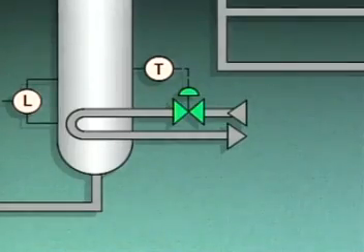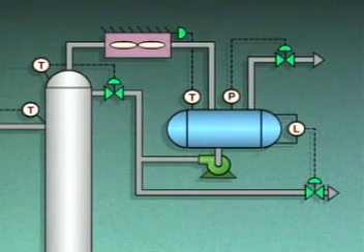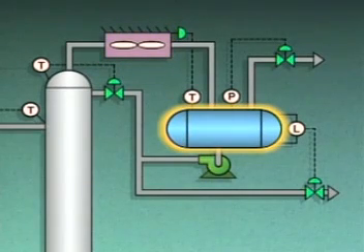The control system's energy balance control loops react to an increase in the bottom temperature to maintain the system's energy balance. An increase in the bottom temperature means that there is a greater amount of vapor flow. As the additional vapor is condensed in the condenser and flows into the receiver, the temperature of the liquid in the receiver increases.